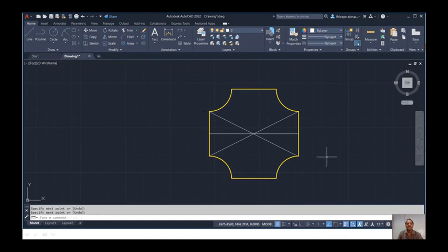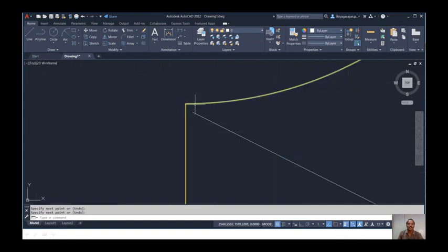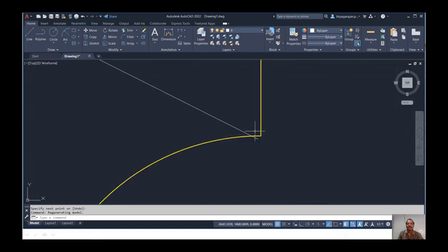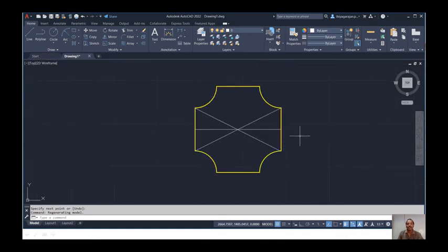It seems that you have drawn it perfectly, but if you zoom in, there will be a gap and no connection. It seems perfect, but it is not. When you take a printout or zoom in, there is a gap in the object. This is not allowed in engineering drawings. It should be perfect, so that is why we use object snap.